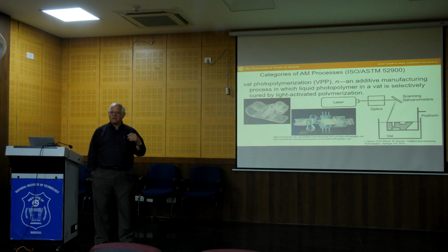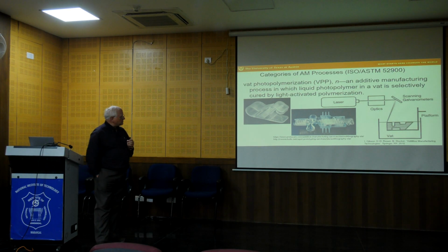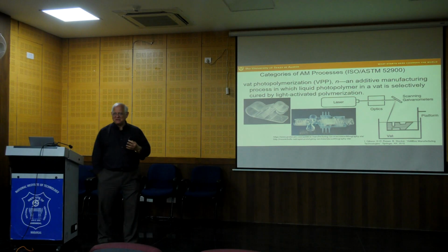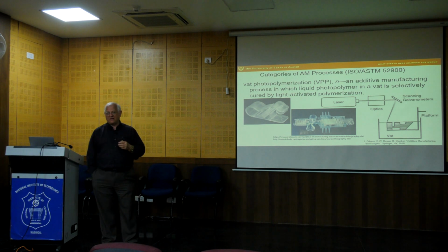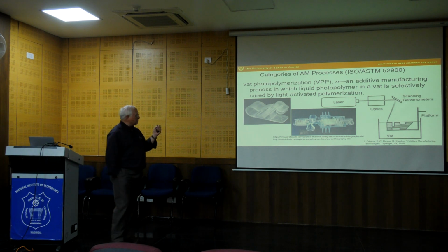The mechanical properties of these parts are not very good. The epoxies after cross-linking are relatively brittle. They just snap. And so to use this for structural applications requires that the part go into service really with no mechanical load. And so that limits the process considerably.